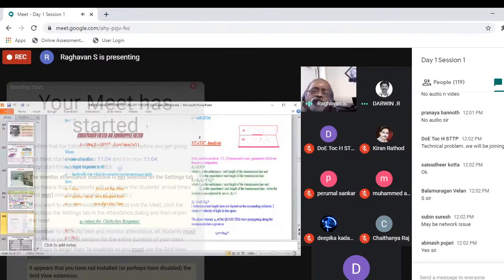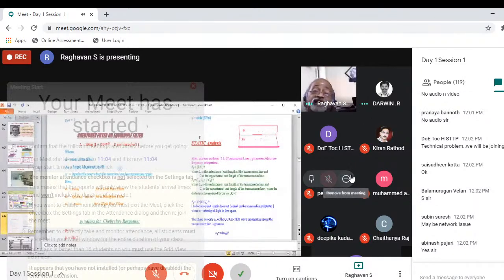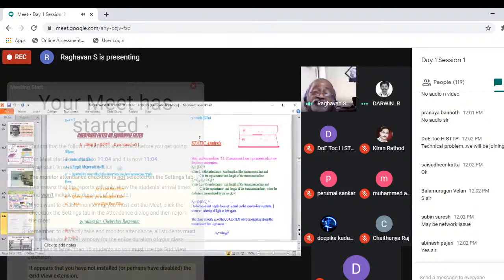Above 12 gigahertz, you can see that W and frequency do not have a linear relationship. That is what we say dispersion. Above 12 or nearby frequencies, for microstrip, you should not go for quasi-static analysis. Likewise, for each planar transmission line, you should see what the dispersion analysis is, then accordingly you should decide. So that is what is meant by static analysis and full wave analysis. In full wave analysis, all those techniques are there.